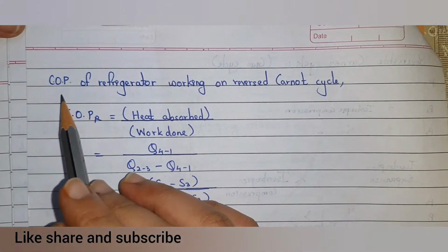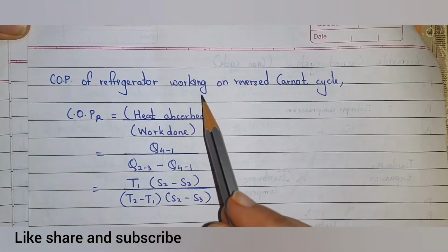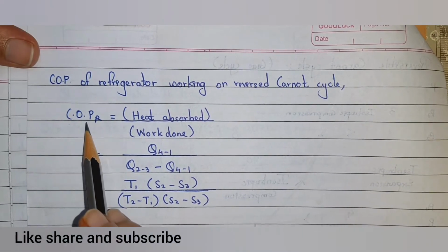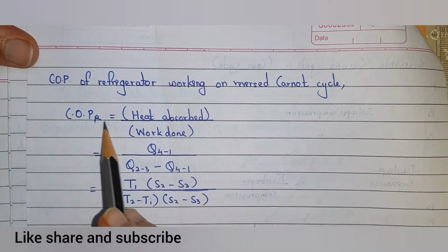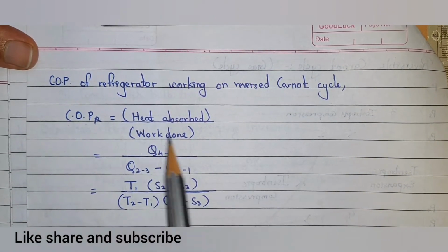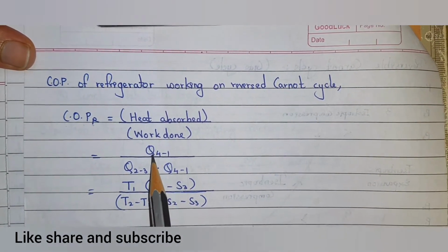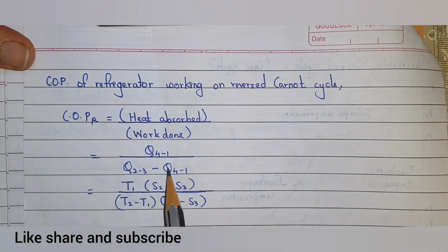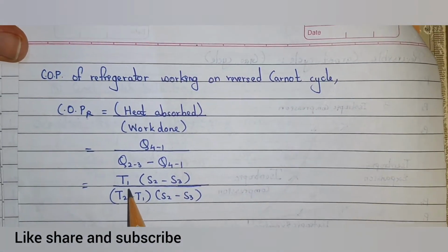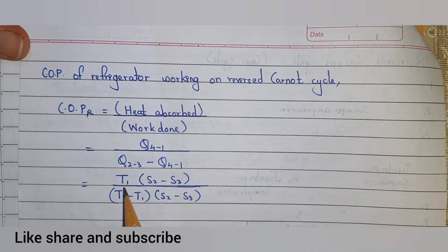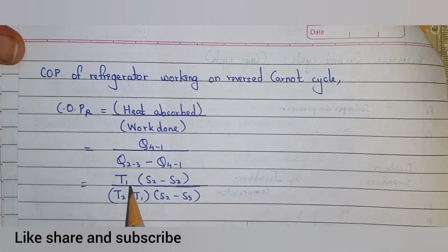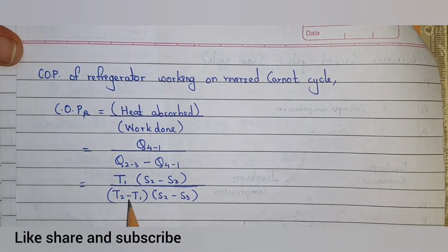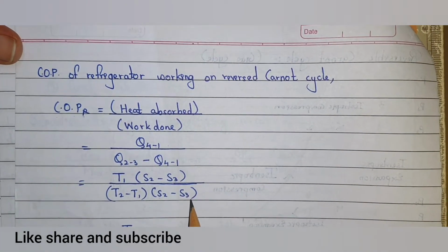Now, the COP of a refrigerator working on the reverse Carnot cycle is given by heat absorbed divided by work done, that is equal to Q of 4 to 1 divided by (Q of 2 to 3 minus Q of 4 to 1). Now substituting the values from equation number 1 and equation number 2, we get T1 into (S2 minus S3) divided by (T2 minus T1) into (S2 minus S3).